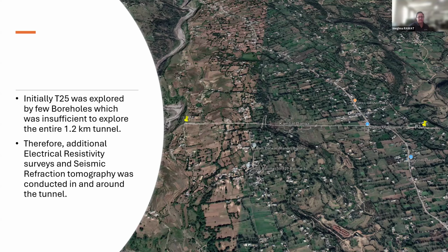So RITES wanted to identify the major water seepage source within the tunnel and propose an effective grouting scheme to make sure the tunnels are effectively watertight, especially during the monsoon season. To achieve this, they suggested creating a 3D groundwater model in LeapFrog Works to understand the groundwater network and the typical source of water. In this model, we have used the ERT data as well as the available borehole data to create a groundwater model.